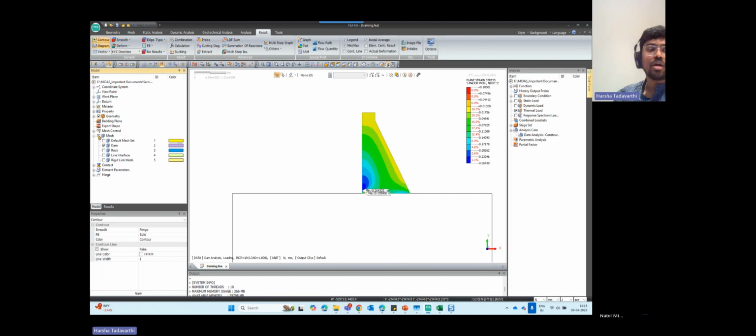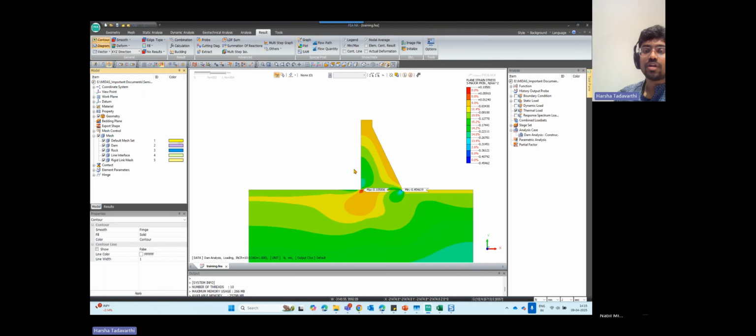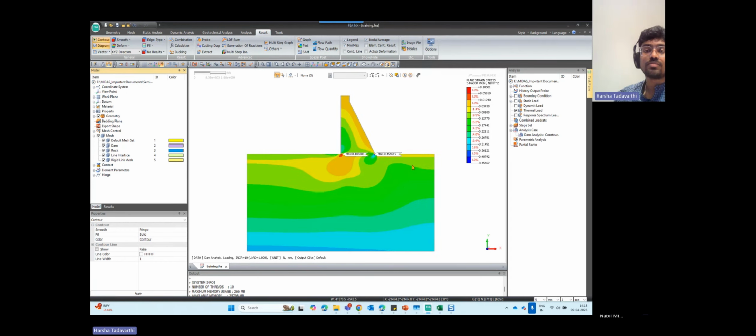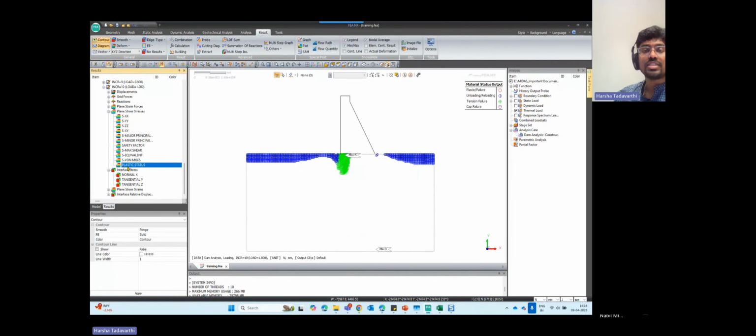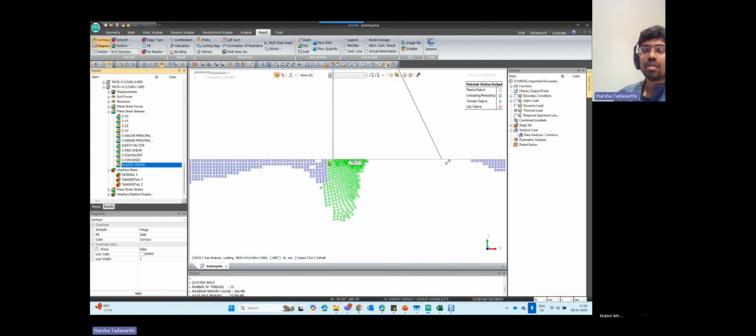But let's say I activate all the rock and everything, and you can find more tensile stresses in the rock and more compressive forces or major principal stresses in the rock. So we can actually see the plastic status of the rock as well. Let's see the plastic status. So yeah, here we go. All the blue color represents loading and unloading failure, but this is the important part.